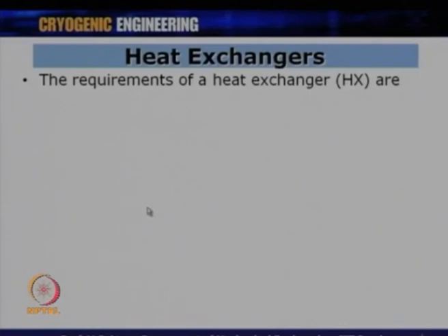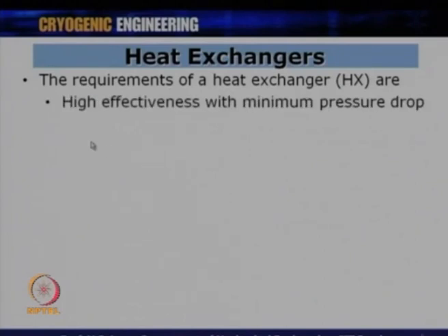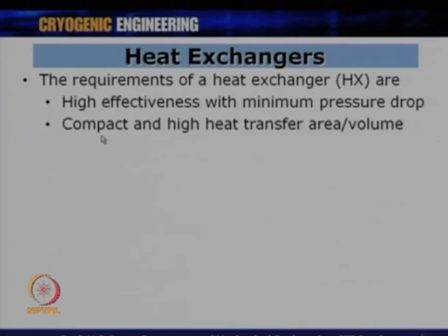What are the requirements of heat exchangers? In order to qualify as a good cryogenic heat exchanger for gas liquefaction, it has to satisfy certain requirements. And what are these requirements? It has to have high effectiveness with minimum pressure drop. It has to be a compact heat exchanger.